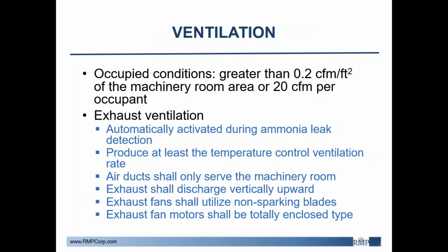For ventilation, IAR talks about the machinery room area and what kind of ventilation should be under normal occupancy, and then talks about exhaust ventilation. Essentially, you don't want to cross-circuit or contaminate your airflow, so having your air ducts and intakes and outlets designed so that you don't have an intake bringing in contaminated air. Also that the temperature does matter sometimes, so accommodating those ambient temperatures, especially in extremely hot or extremely cold climates, you don't have a problem with that.